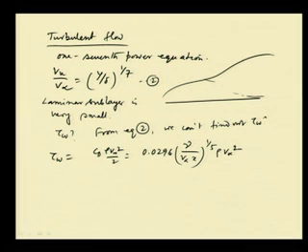This is the expression of tau w that we have to use, and it is valid for a Reynolds number less than 10 to the power 7, so for quite a high value of Reynolds number turbulence this expression is applicable. So, we can use this velocity profile in the momentum integral equation. That is what we will write now.